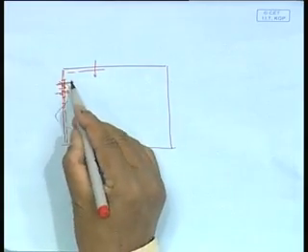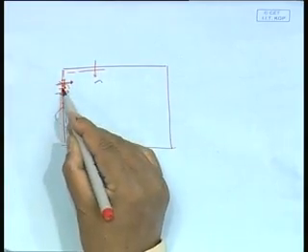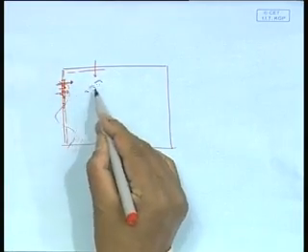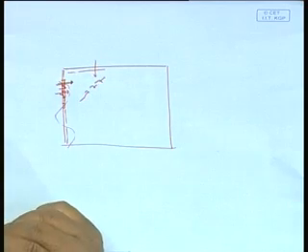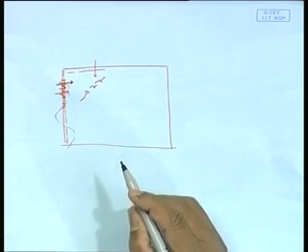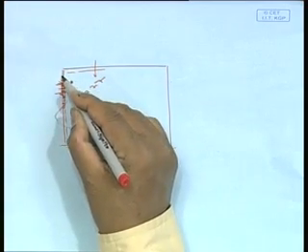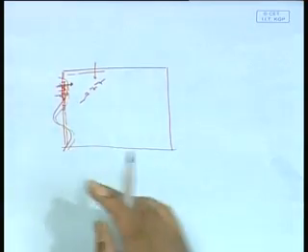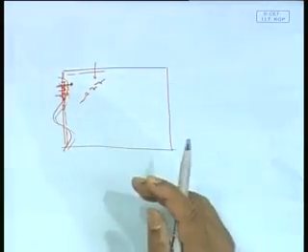How do you know? I will also tell you this. Suppose I move this one more, the crest would come here. This one slightly less, the crest would come here. This one slightly less again. So you end up getting a wave like that. It is a very complicated theory, but you can move the wave maker like a snake, where when this one is here, the next one is here, the next one is here, and then you can make a directional wave.